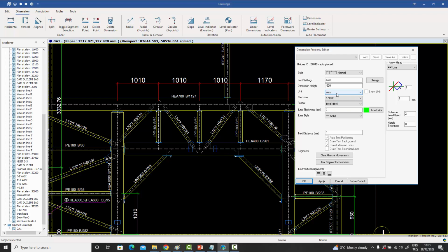And besides this unit option, there is another option for the precision. Previously we didn't have this variable directly in this form. Now we have these different precision levels, and the first ones are typically used in millimeters. So rounded off to the nearest 0.25, rounded off to the nearest tenth or a hundredth or a thousandth. But now we have added these three extra ones, which is rounded off to the nearest eighth, nearest 16th, and the nearest 32, 1 over 32. So this is another precision variable which we've added to the dimension.